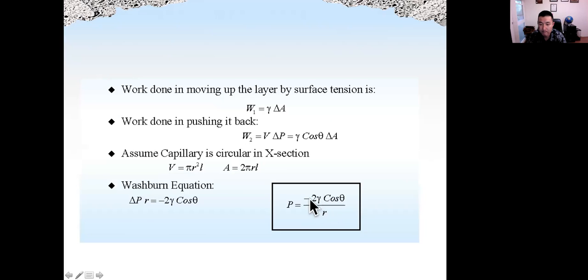Gamma is the surface tension for mercury, which is also a fixed value. Based on the so-called Washburn equation, a famous equation, we have a correlation between the pressure we applied and the size of the pore. Other information, including gamma and theta, is pretty much fixed.